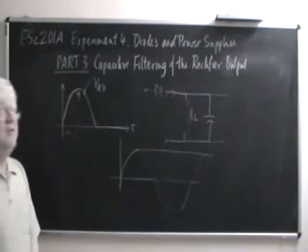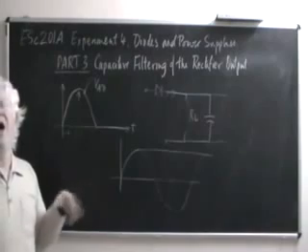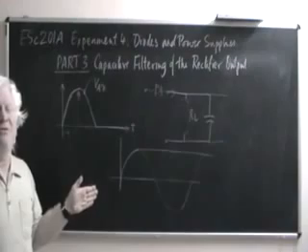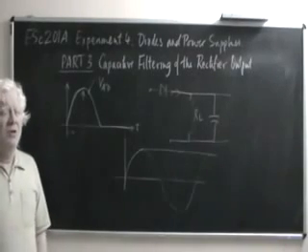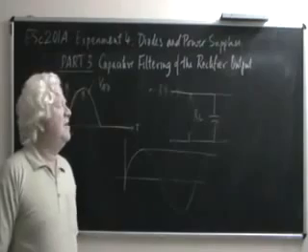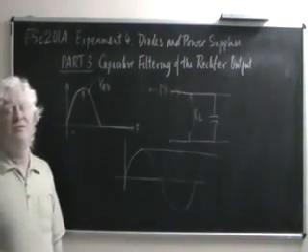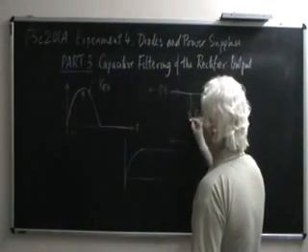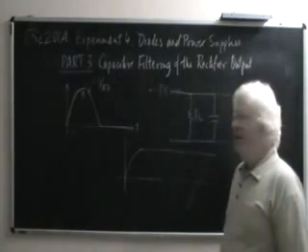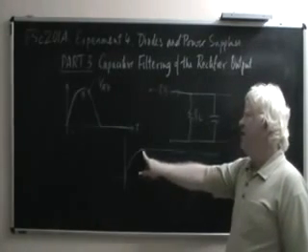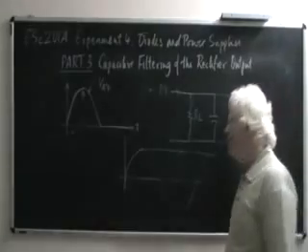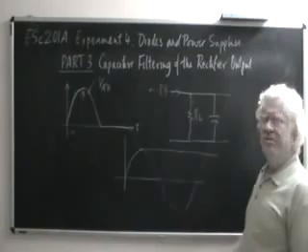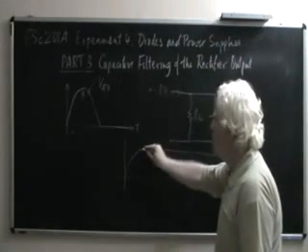However, if we have any kind of resistance across which the capacitor can discharge, then a very different thing happens. If there is any scope for the capacitor to discharge, such as by having a load resistance, let's reintroduce it over here, then after this point the capacitor does indeed begin to discharge, and instead of its voltage remaining constant for the rest of the future, it starts drooping.